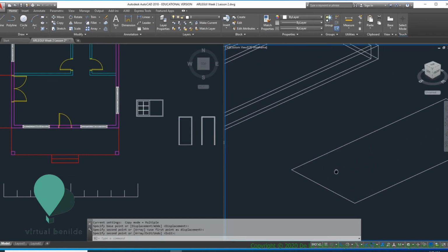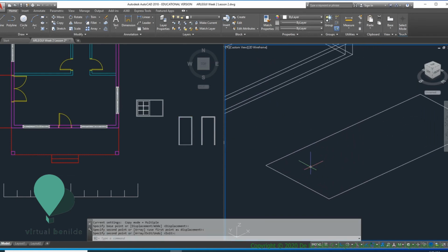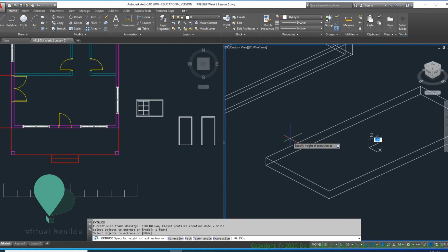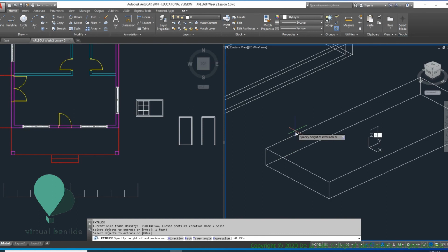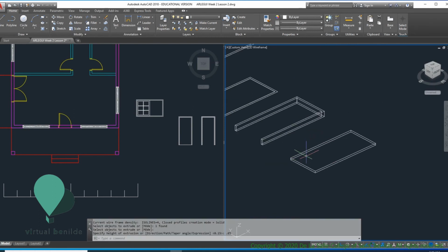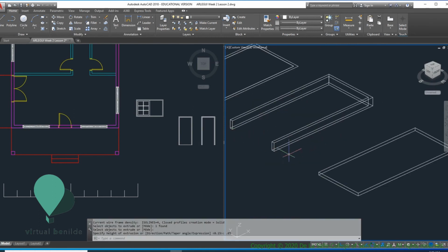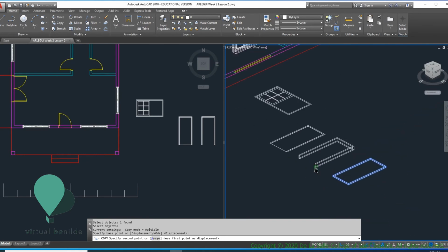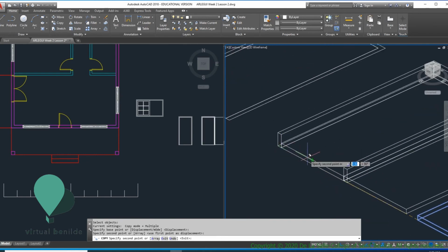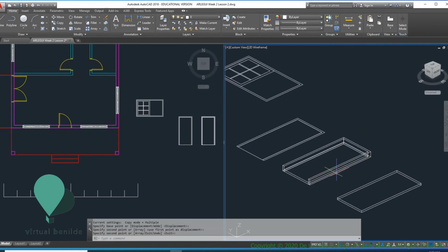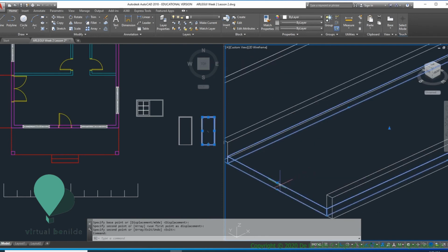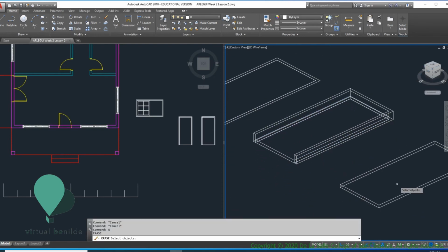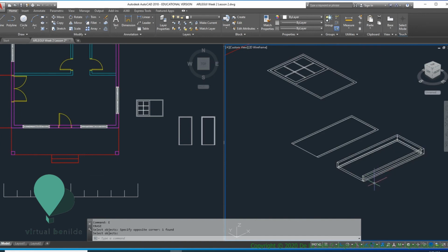It's going to be 2 inches in thickness, or 0.05. Extrude this, ext, by 0.05. There you go. So you need to place this like that endpoint to this endpoint. Okay, I can erase that extra.